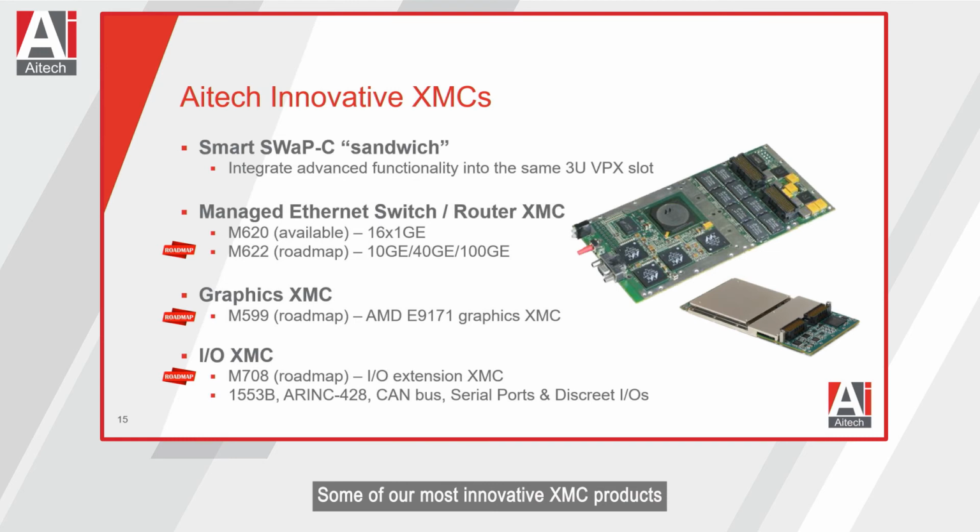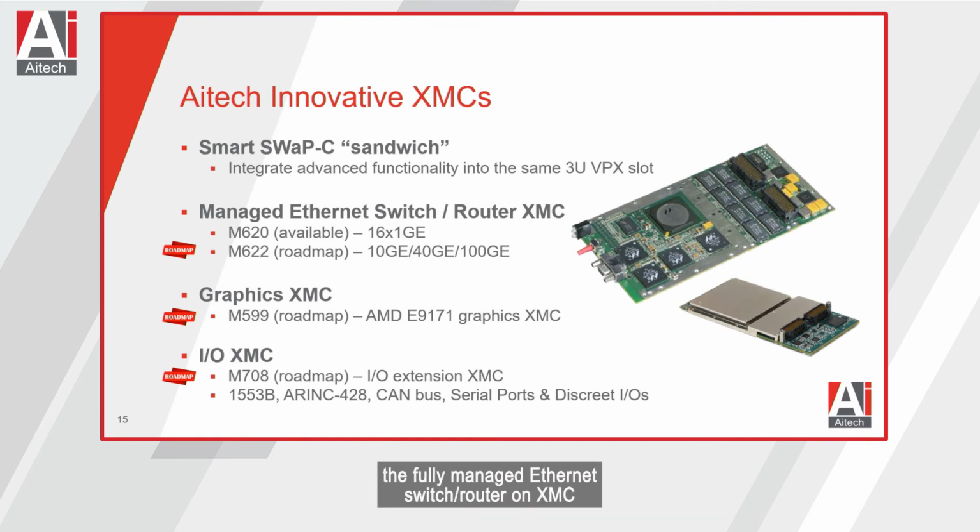Some of our most innovative XMC products are managed Ethernet switches like the M620 and the M640, which support Ethernet speeds up to 1 gigabit Ethernet and up to 16 ports on the M620, the fully managed Ethernet switch router on XMC. This creates a very efficient combination of XMC and switch in a single 3VPX slot.